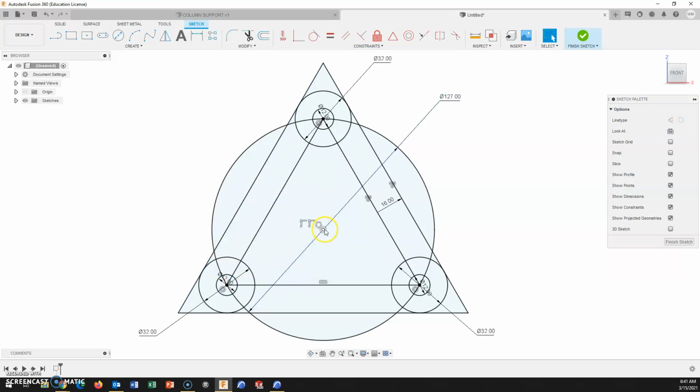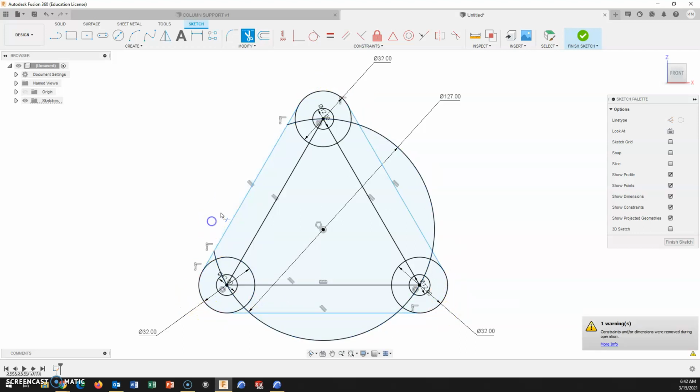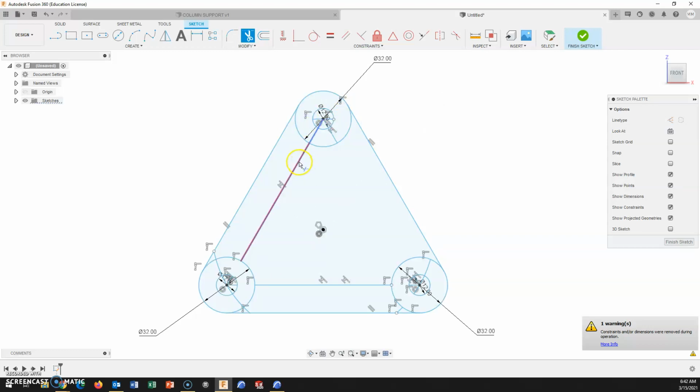One thing later on, we will not be able to find this. Oh yeah, we'll have the origin. We can trim. Instead of trying to come in here and select each individual area and maybe missing one, the trim tool, if there is a bounding body, it will allow you to trim to that adjoining body, and really just as a means to clean up your sketch. You do not have to trim. You can still come back and select the individual areas. But trimming allows you to select line segments to remove them.